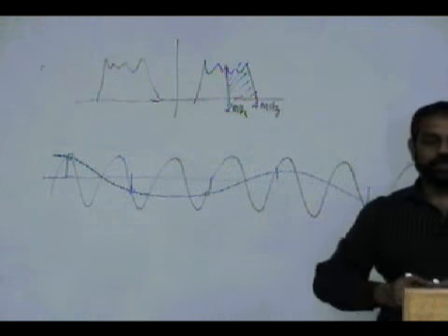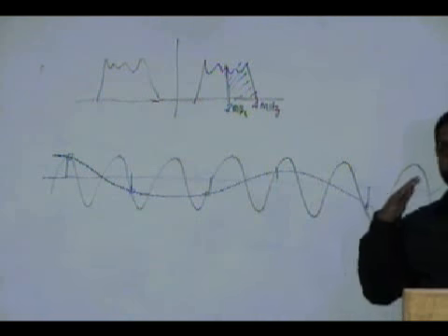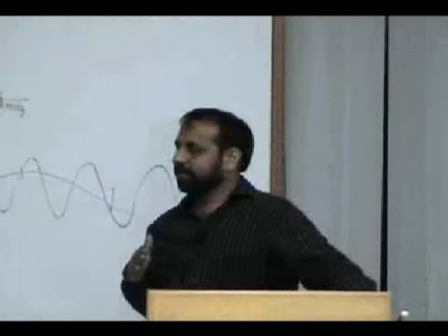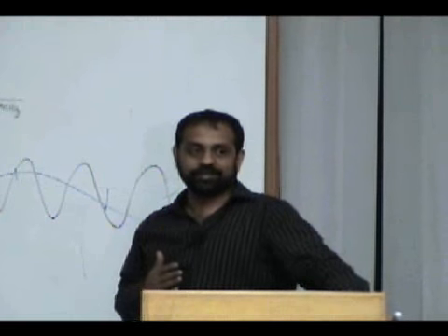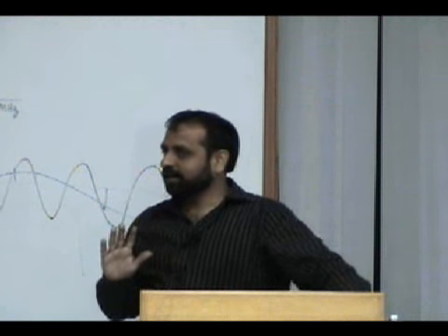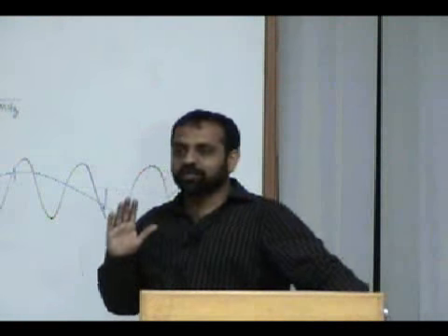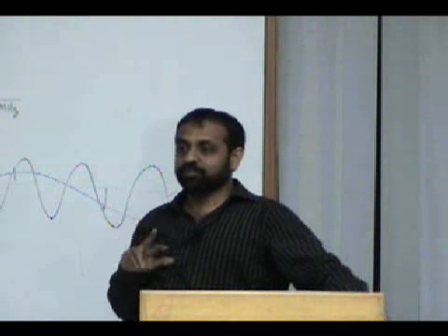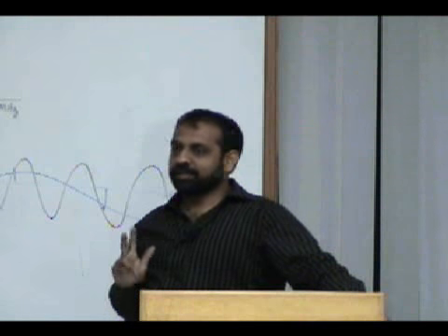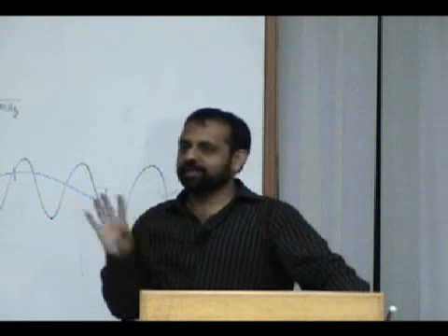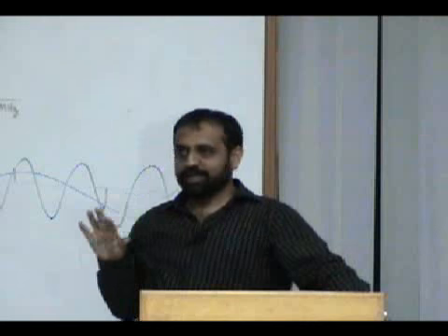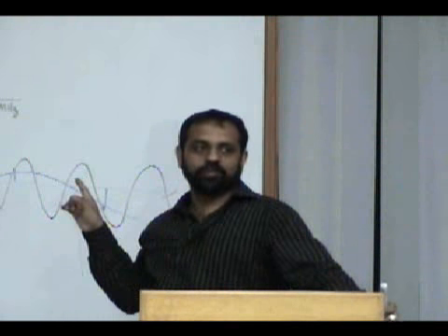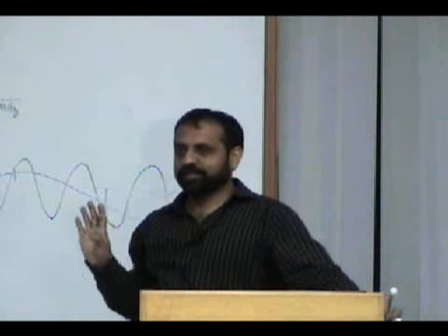So for example, you say to sample 4 megahertz, I must sample it at what rate? 8 megahertz, but you only sample at 4 megahertz. So at 4 megahertz, what frequencies are you precisely capturing? 2 megahertz. What will happen to frequencies 2 to 4 megahertz? They will come and corrupt the 2 megahertz frequency. You will get nothing. Okay? We'll see how, but literally, if you don't sample it appropriately, you may just get garbage, nothing else.